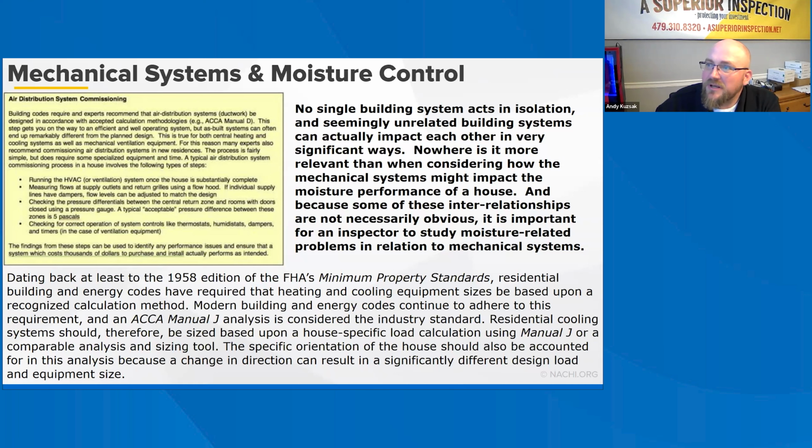Sealed combustion chambers should not create moisture problems. The use of sealed combustion HVAC equipment is ideal because it helps to alleviate potential backdrafting, and it also helps to control pressure differences across the building envelope. Controlling air pressure differences across the building envelope helps to minimize air leakage and migration of moisture into building assemblies.